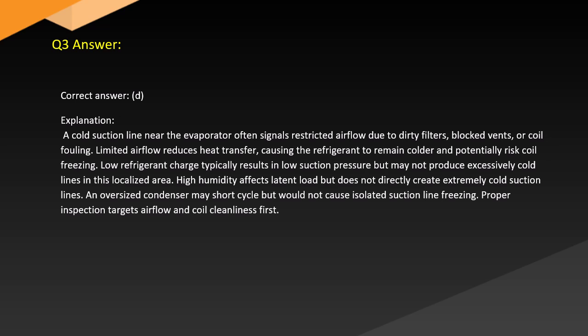Answer. Correct answer: D. Explanation. A cold suction line near the evaporator often signals restricted airflow due to dirty filters, blocked vents, or coil fouling. Limited airflow reduces heat transfer, causing the refrigerant to remain colder and potentially risk coil freezing.